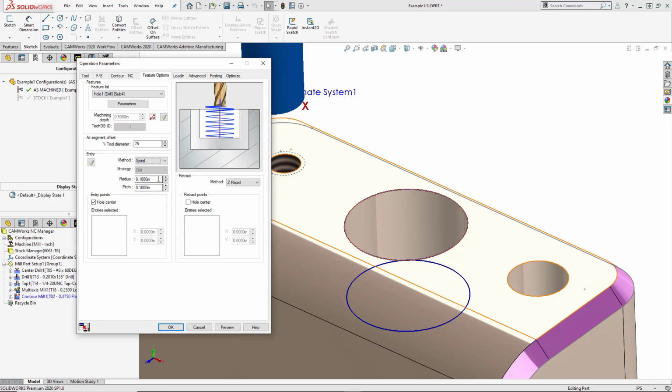The formula that I find useful is based upon radius. If the hole diameter is 3/4 of an inch, the radius will be 0.375 minus 0.1975, which is the radius of the tool plus 10 thousandths for final cleanup at full depth of cut. After selecting Tab, CAMWorks will calculate the required value of 0.1775 automatically.